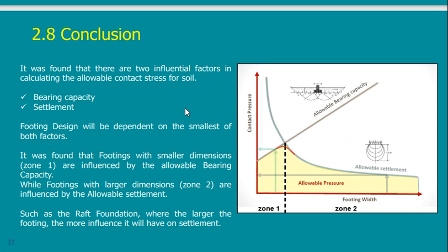It should be like this. Usually in a very elaborate soil report, you should give me something like this, telling me for the foundation that you have, you should draw for this foundation. Suppose I need here to construct a foundation. You are going to assume different breadths, and each time you are going to calculate the allowable due to settlement and allowable due to shear, and draw the drawing and give me this.